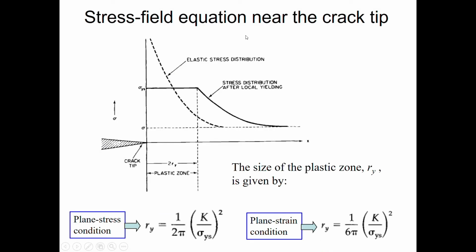Stress. This is the same. The stress field equation for near the crack tip. The same situation where you have applied stress here. This is the sigma u stress. The only limit that you have to apply is in your elastic region. Once beyond this, you will be in the plastic region.